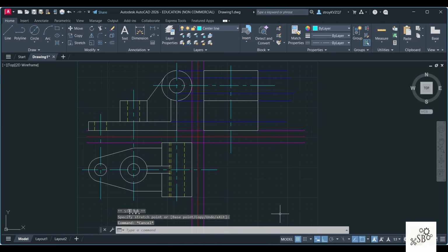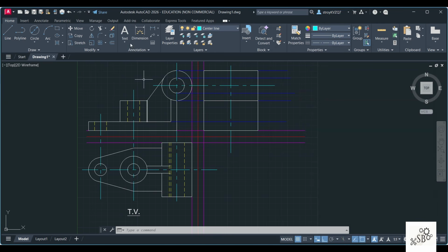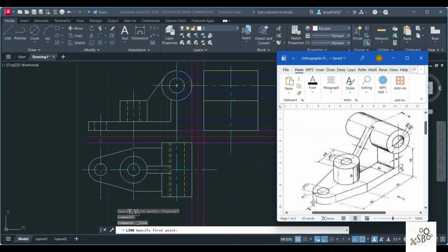From this height, from the side view, if you observe, you are able to see this cylinder. These are two lines joining up to the height of 35. That is this line which has to be projected. If I just project this line from here, let's choose 0 line from here, just trace. You can see this is the same line which has been drawn here. So I will have to draw from here 35, the same point, and from the side view, this distance is going to be 45.